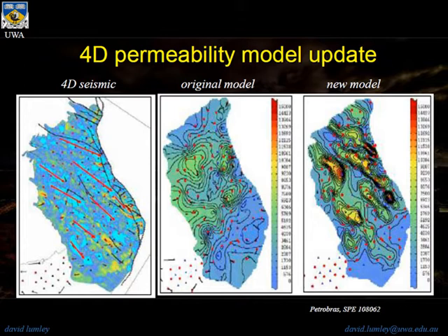So the idea is capture it at the source, separate CO2 from whatever the other products are in the stream, compress that CO2, pipe it somewhere, and inject it back into the earth where it came from. And of course, the idea is to inject it usually at least 1 kilometer or more depth, where it's supercritical, and you inject it into a porous permeable formation. It might have traps and so forth. It might be a depleted oil field, but actually there's about 1,000 times more storage opportunity in saline aquifers.